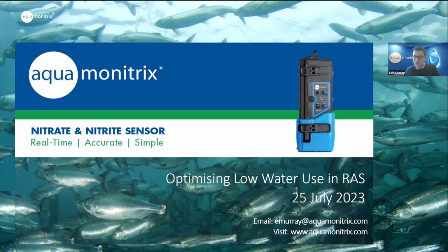Turbidity is not an issue, things like that. So the typical challenges and problems that direct UV absorption measurements experience, we overcome by our anion separation, and also the fact that we're using the matrix elimination technique with the sodium chloride mobile phase.